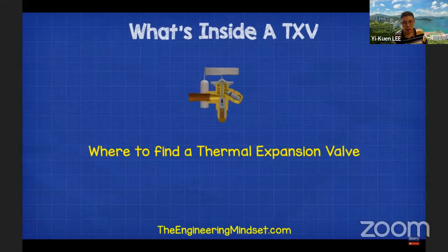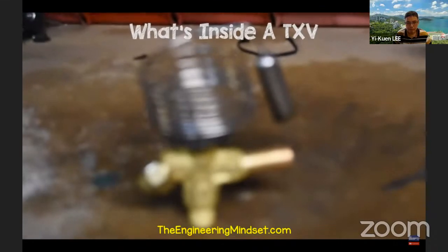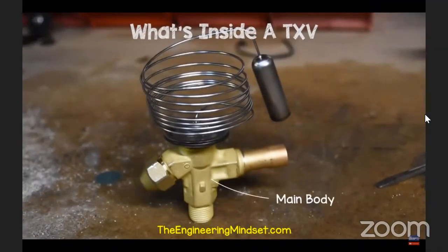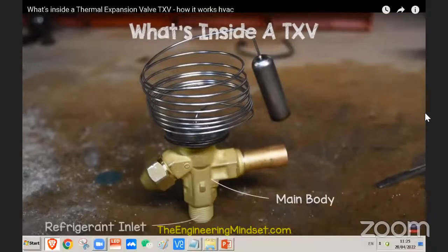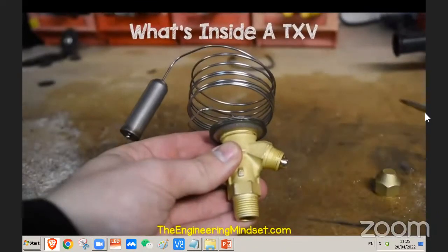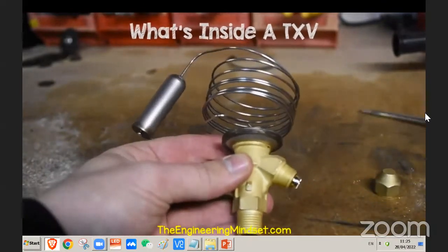So where do we find the expansion valve? Expansion valves sit between the condenser and the evaporator in a refrigeration cycle. In this model, which is a T2 thermal expansion valve, we have the main body, which is made from brass. On the body, we have the refrigerant inlet at the bottom of the valve, then the refrigerant outlet at the side, and on the other side we have a cap which can be removed. Under that cap is a screw which is used to manually adjust the superheat. We'll see how that works later on in this video.